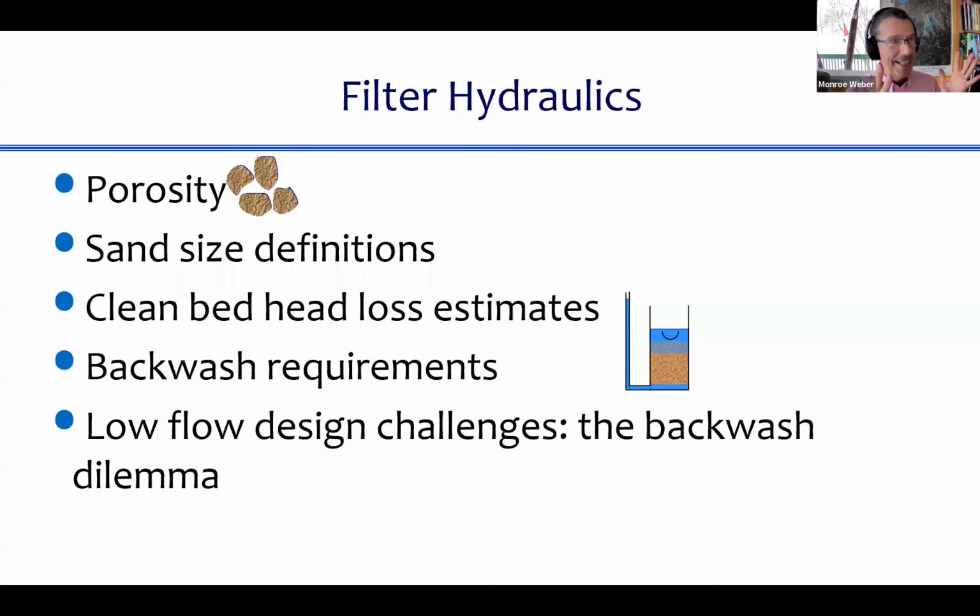So today, now that we've seen fluidized beds, I want to go over some concepts that are important for understanding how filters work, ranging from porosity, sand size, the head loss, how much pressure drop there is as a fluid moves through porous media, and how much fluid do you have to push up through a sand bed in order to fluidize it. So we'll do the math for that. What's lovely is it's a relatively straightforward calculation to get a very good estimate of that.